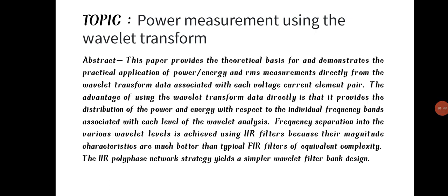Frequency separation into the various wavelet levels is achieved using IIR filters because their magnitude characteristics are much better than typical FIR filters of equivalent complexity. The IIR polyphase network strategy yields a simple wavelet filter bank design.